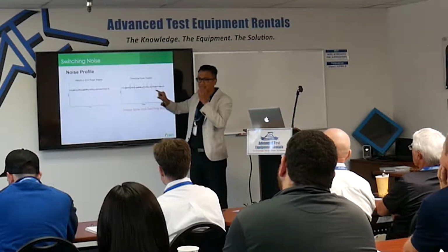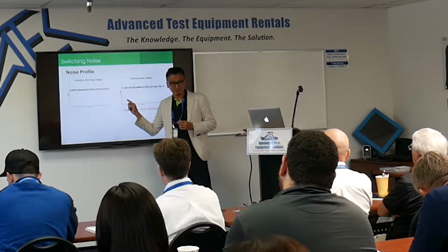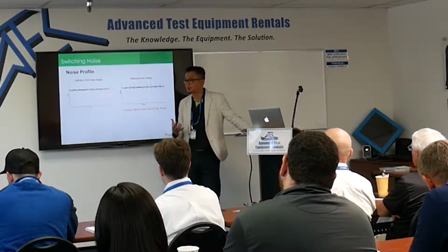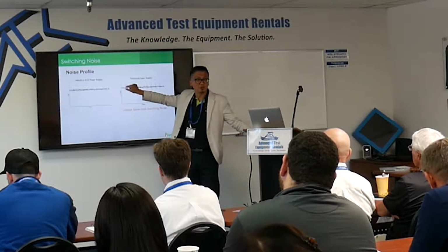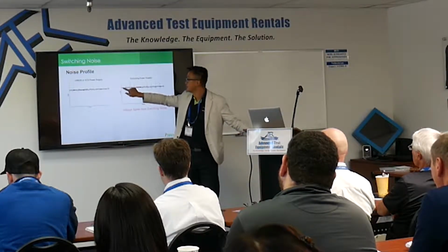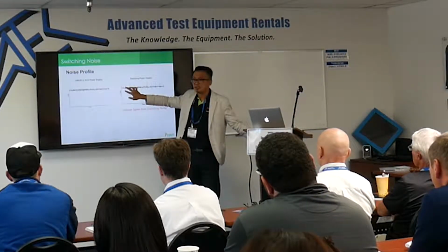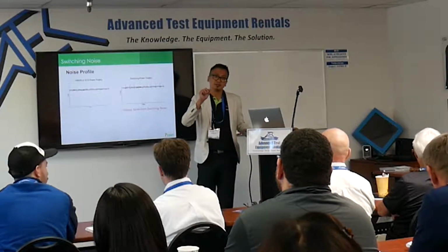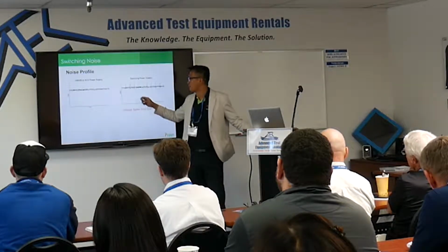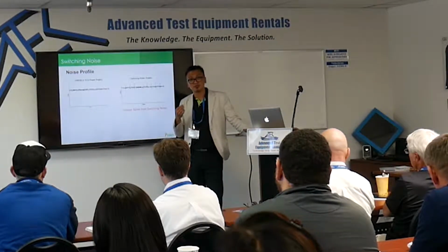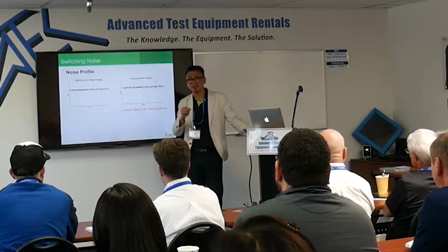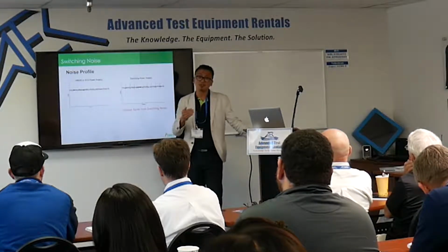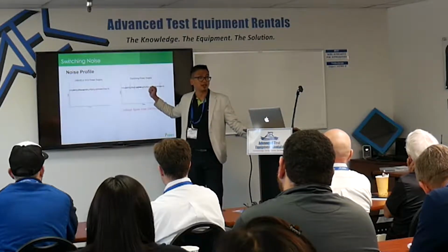But nowadays, the technology is getting better. And the power supply manufacturers will try to make the switching noise as small as possible. So when you see the sine wave at the output, you will not see it so obviously. They suppress the switching noise very well. So it depends on how much THD. When you read the specs of the power supply, you can check how much THD they can achieve. The lower THD means they have lower noise.